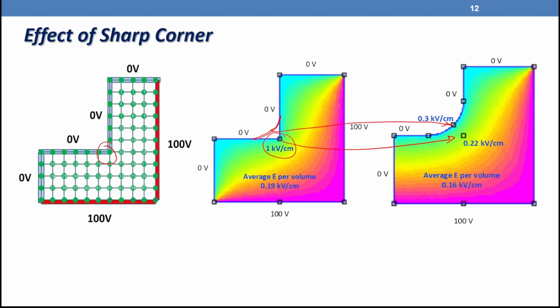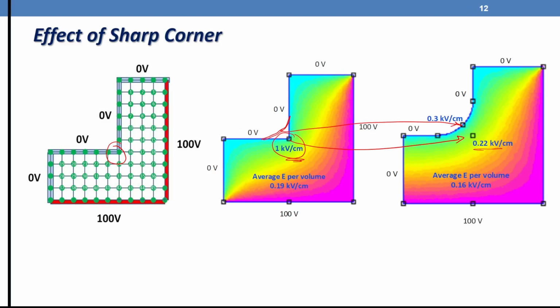What are the benefits? The manufacturers of electric panels nowadays use bus bars without sharp corners to avoid high stress, and they use round corners here to lower the electric field stress for these bus bars. And the finite element analysis for something like that helped us to see the pattern, or how the electric field is distributed through this figure.